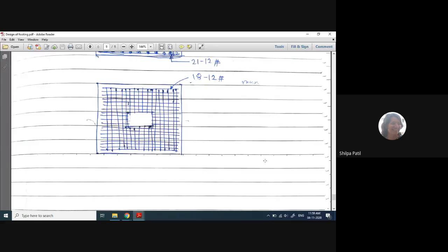Now, this is the design for footing for an axially loaded column. The design steps are lengthy, but easy to understand, not so difficult. Similarly, for a uniaxially loaded column, that is, a column with axial load plus moment, that also has to be considered, because in your term work we have such columns which carry the moment along with the axial force.